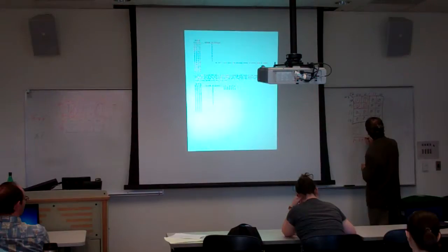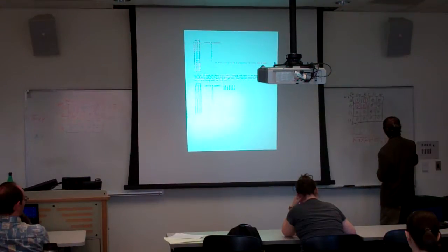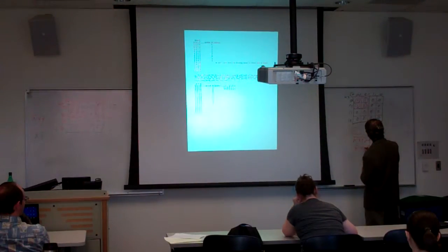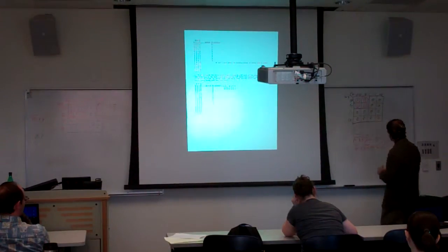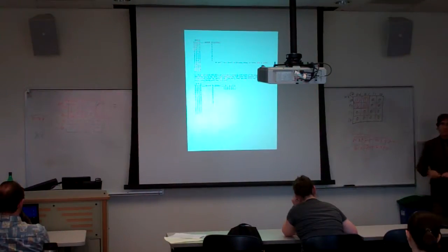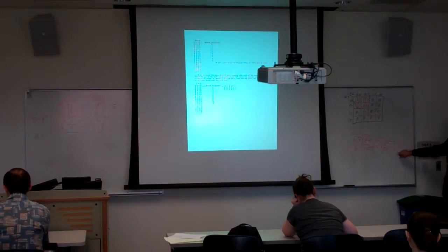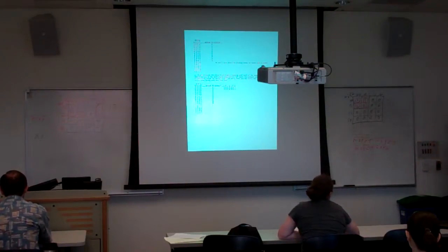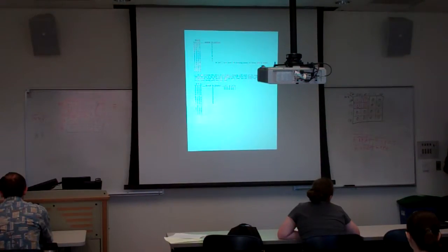Okay, and you would get W bar, X bar, Y bar, Z bar, or W bar, X bar, Y bar, Z, or W bar, X, Y bar, Z bar, or W bar, X, Y bar, Z. Okay, logically it's exactly the same thing. Well, it's not exactly the same thing, but it's going to give you the same pattern of 1s and 0s. Okay, this is your original sum of products that we first did from a truth table, where we just found the product that corresponded to each row, and then we ORed them all together. This is what you would write just from inspecting a truth table and writing down the expression for each of the points where your output column is a 1.